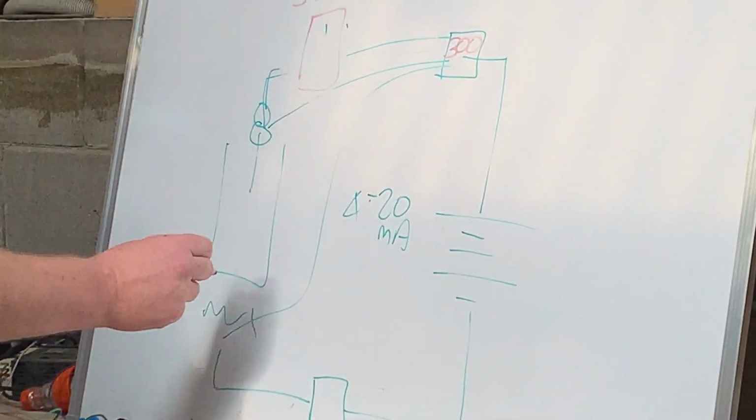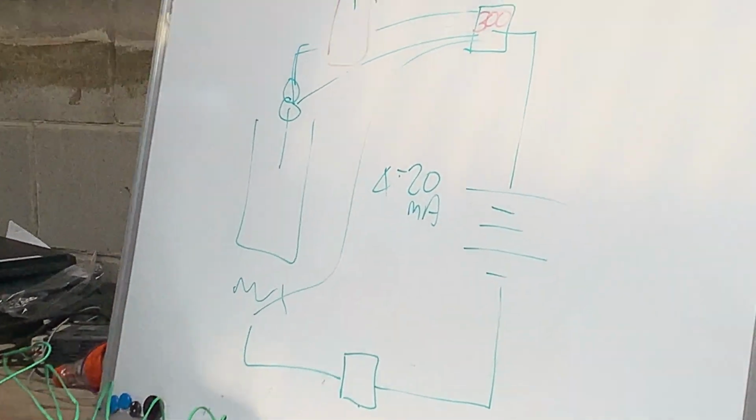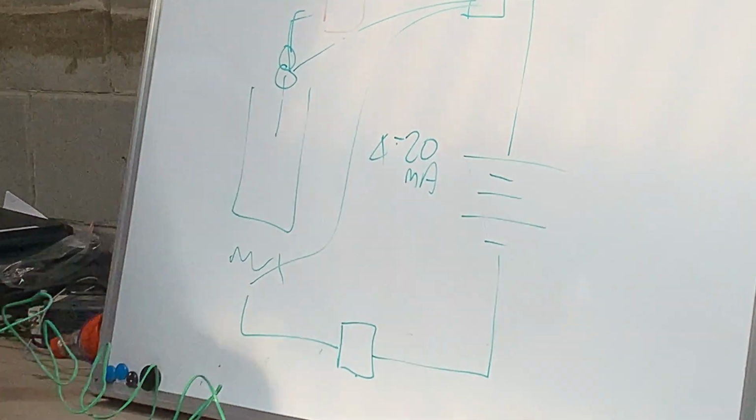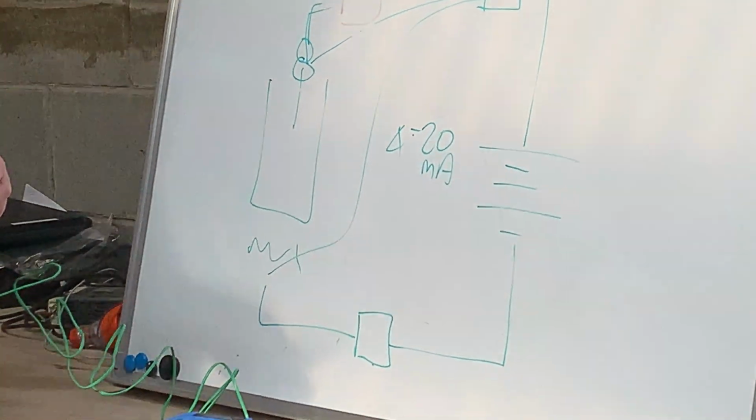You should also see the flame behave as you'd expect at 300. So if your set point was 400, you'd expect the flame to be going hard. If your set point was 250, you'd expect the flame to be nothing.